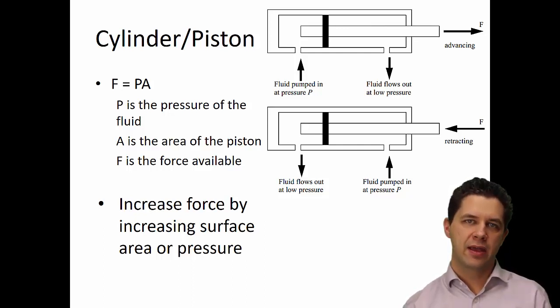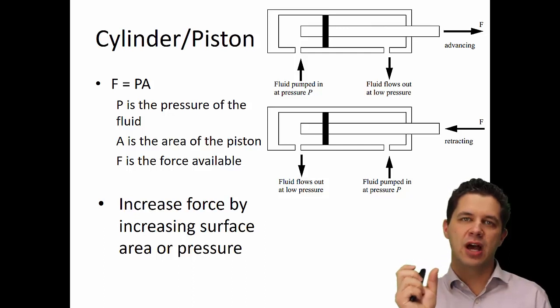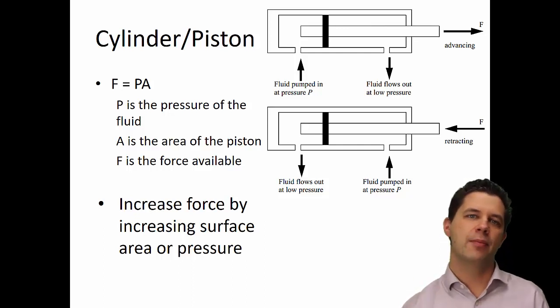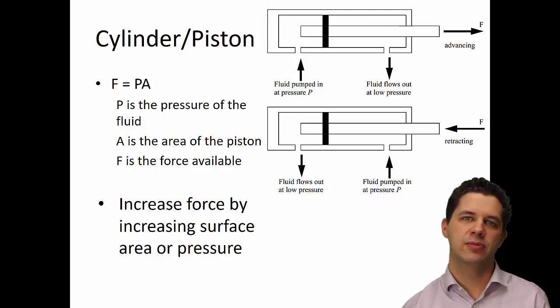We apply our fluid or gas into that first inlet, and everything inside that second inlet is pushed out through our exhaust point. Likewise, when we're moving the other direction, it's pushed out by that other exhaust point. When we're using a hydraulic system, we don't exhaust the fluids out into the atmosphere. We'll send them around our hydraulic circuit and keep them circulating.